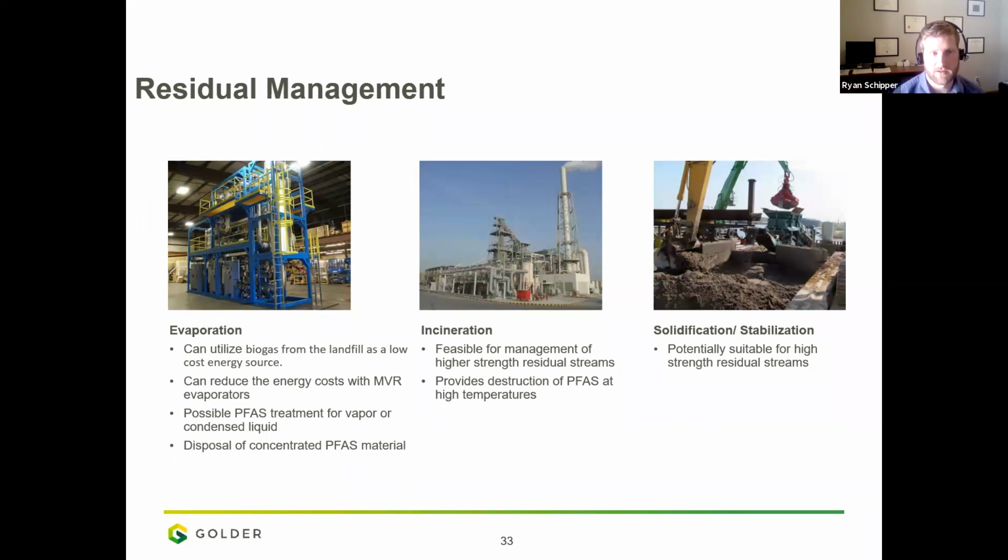But with many of the technologies that we discussed, there's some residual that's formed. And so, what do you do with that residual? Well, evaporation is one option. You can concentrate that residual up further. There's a limit to that then. Once you get down to this low volume, if you will, you're pretty much looking at incineration at a proper incineration facility, or solidification stabilization to try to bind that PFAS so that it doesn't release back into a landfill or back into the environment.